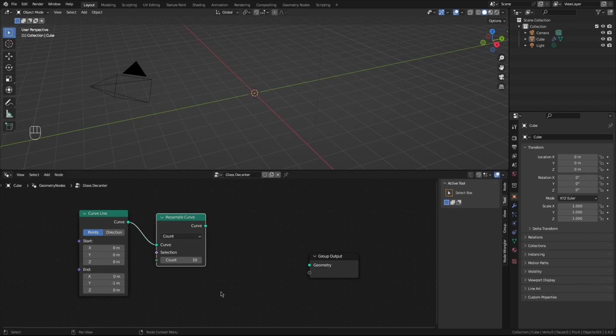I want to resample the curve into 8 points. The reason for this is we want to control 6 of them. The last one will be the center of the bottom of the decanter, and the one next to it will be about halfway over. This is because NURBS tend to form very smooth lines, and it takes 2 to get anything like a reasonable flat bottom on the bottom of our decanter. And now we have a line.